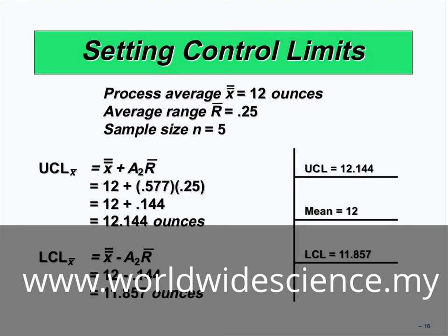You should take the data and the mean of each sample to this chart, and then check whether all of them fall inside the allowed area or not. Allowed area means between UCL and LCL. All of the blue spots should fall inside this area between UCL and LCL.